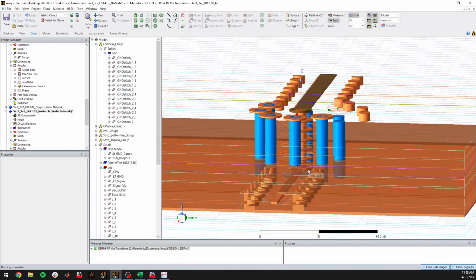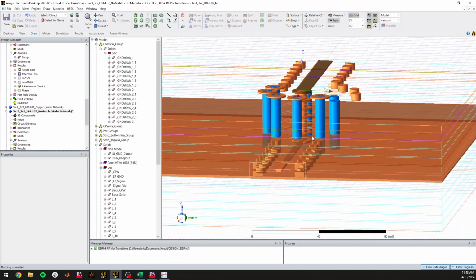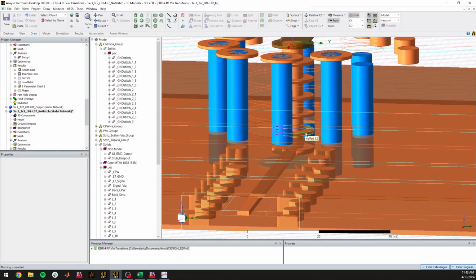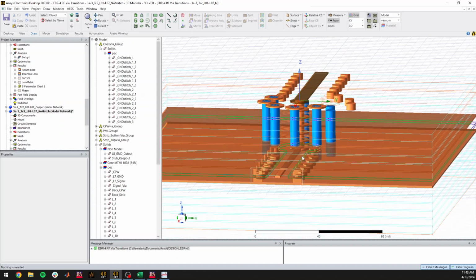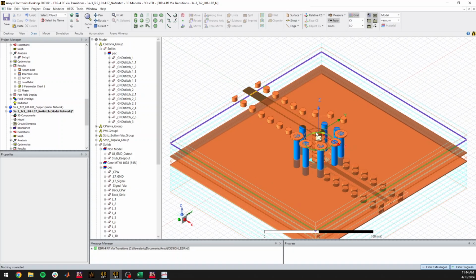But it is very important to, once again, keep in mind you need these via pads on each layer in a micro via case. This might not necessarily be true for a through via, but for micro vias, stack micro vias, you are needing to model, or at least keep in mind that this exists. So I'll show here, this is basically the first pass out of the design.